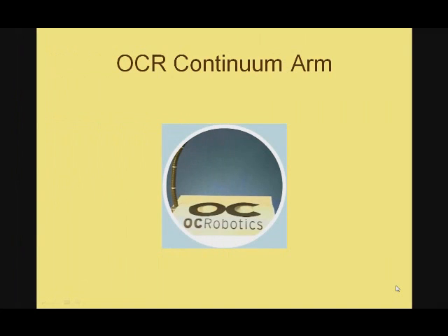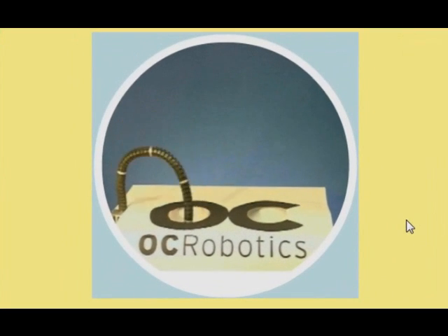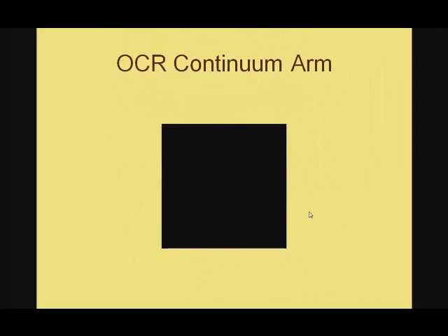As we will see, the Jacobian is very effective in solving the inverse kinematics problem over trajectories of the hand. In other words, creating the configuration or the shape of the robot to let the hand do what you want for conventional robots. But it's also effective for unconventional robots like this. This is a continuum or snake-like robot manipulator built by ECE Robotics. Here the robot is taking its end effector through the logo of the company, and creating the right shape of the robot to make that happen is fairly complicated. But it's done effectively here using the Jacobian.